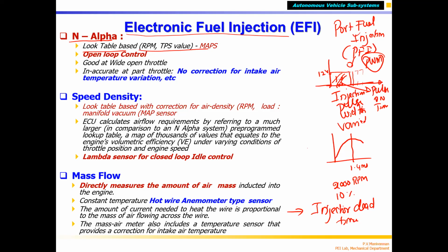We know the injector is a solenoid, an electromagnet. So it is an inductor with resistance, because the coil has inductance with resistance. So it is called an RL circuit. This is your injector's equivalent circuit, with resistance and an inductor coil. Together they form what is called a first order electrical system.